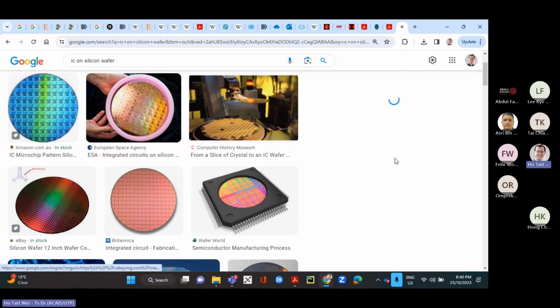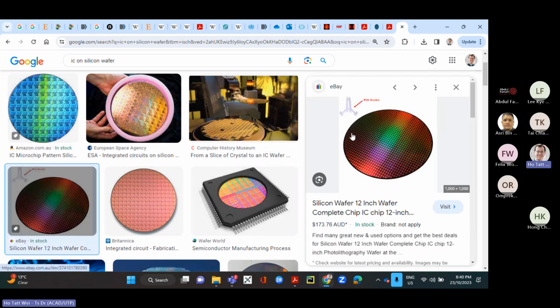And nowadays, within one wafer, let's say the chip on this side and the chip on this side, even though it's the exact same design, exact same situation, they may have different parameters. So this is within-wafer variation. And you see that because, again, as these wafers get very big, they're not 100% flat. There's actually a slight curvature, and the quality of the chips on the side may not be as good as the one in the middle and things like that. And like I said, you look at this wafer, it looks super flat, but on a microscopic scale, there may be bumps. This thing is not exactly straight and things like that, right? Because it's a bit heavier in the middle and all that.